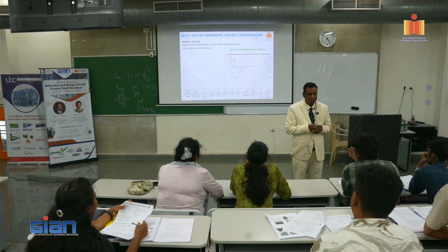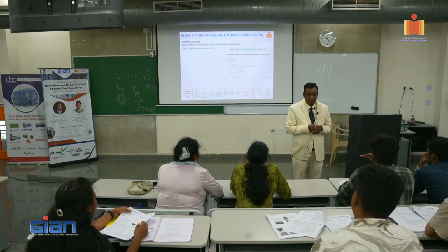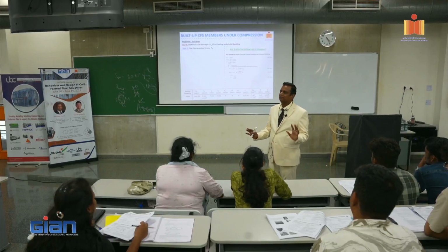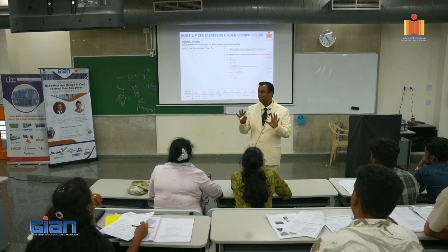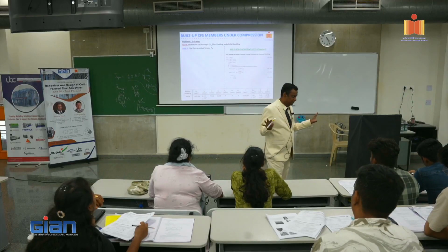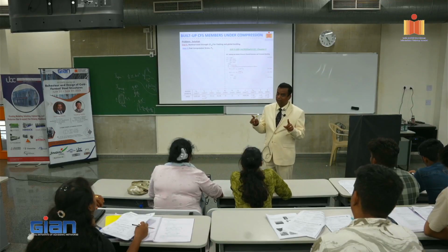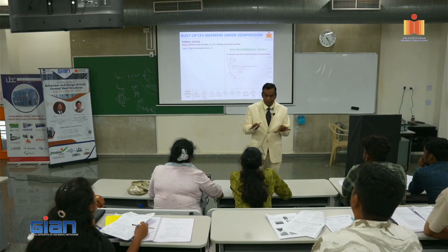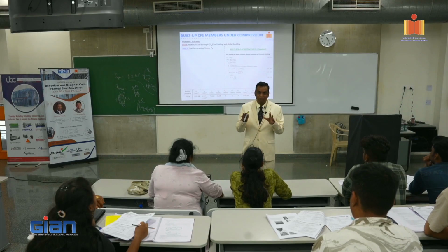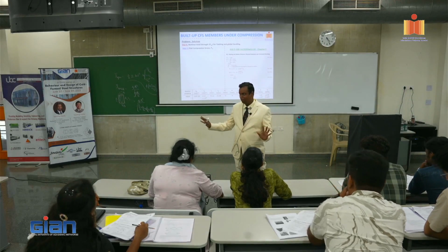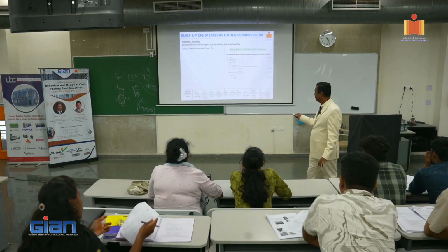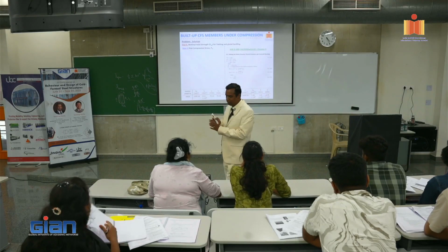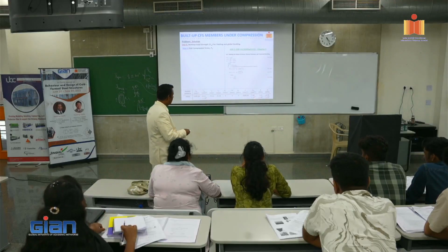Phi square is reduced from the ideal curve, reduced for imperfection. Now what is that? It's a parabola. I'm simply asking mathematics. Never forget your high school teacher ever in your life, especially your math teacher. He is more than God. I'm telling you. If people in high school teach mathematics perfectly, I don't think there will be any shortage of engineers in our country. Math is the foundation for everything. Right? So 1 by lambda sub c square indicates it's a parabola. So it means that when you exceed the Lakshman Rekha of 1.5, you have to use Euler buckling. Right? 1.5 is the cutoff. When it is less than that, you have to use this equation.